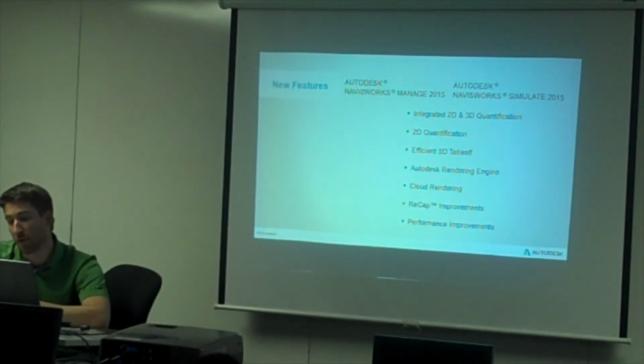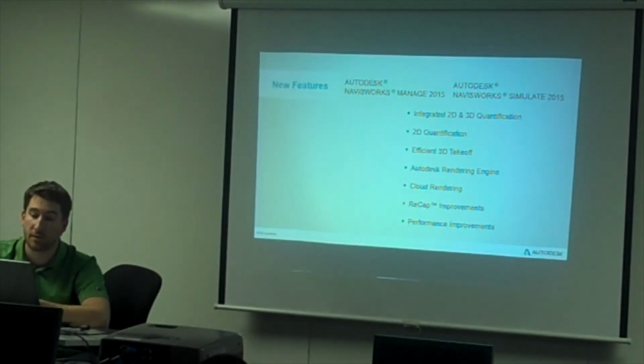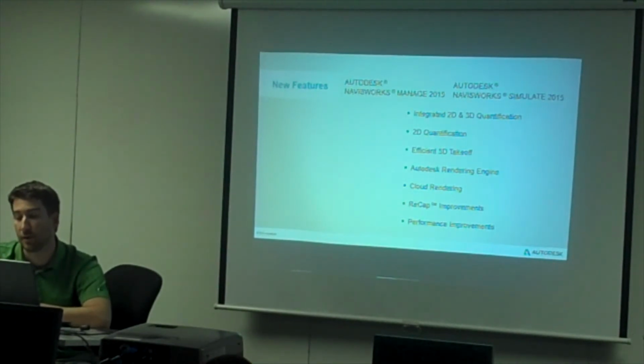And then once you've brought all those together, then you can do a couple different things. You can navigate the model and visually inspect it to determine if anything's not going to work. You can do some quantification. So there are some enhancements that we're going to talk about around quantification. So can you do a takeoff on those model elements? The answer is yes. Also, the product is known for coordination, or what they call clash detection. That's a big reason people use Navisworks.